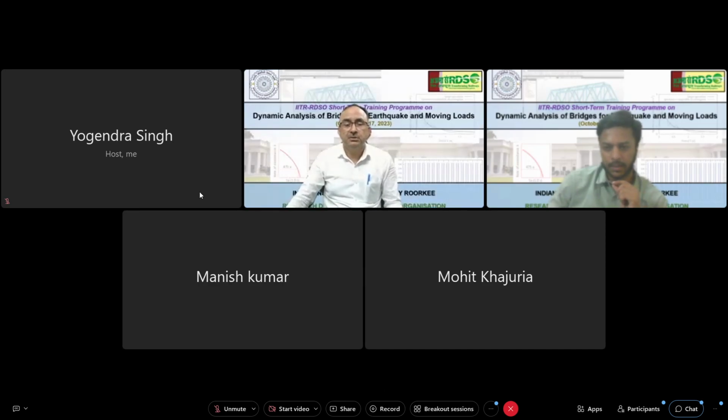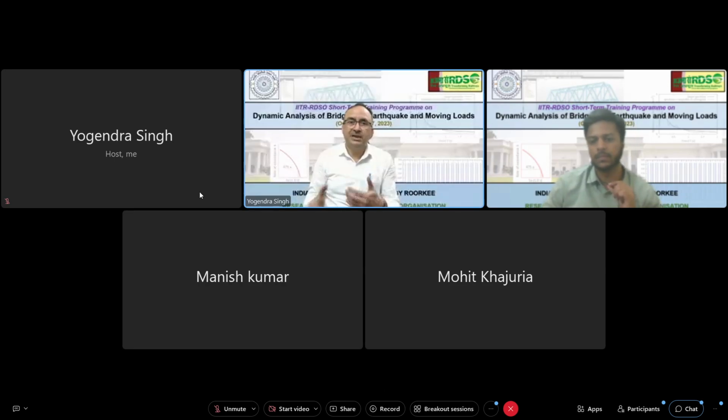Mr. Abhishek is asking, while doing time history analysis using already recorded data, how the intended lifetime of the structure is accounted for? Okay, so intended lifetime of the structure we are taking into account in the return period of the earthquakes, which probability of occurrence we are taking. For example, in case of buildings, we are considering, let us say, 10% in 50 years. In case of bridges, we are considering 5% in 50 years. So, sorry, 75 years. So that changes.